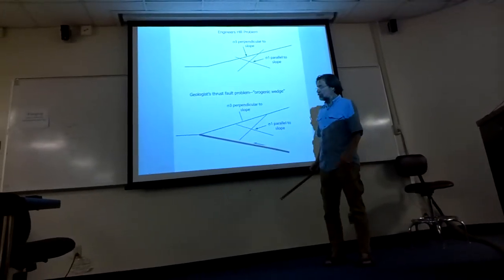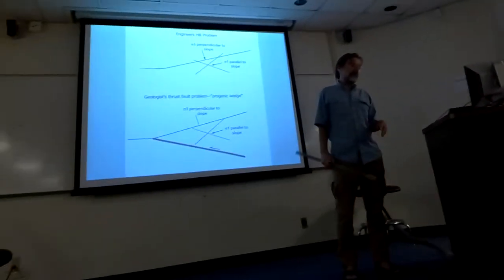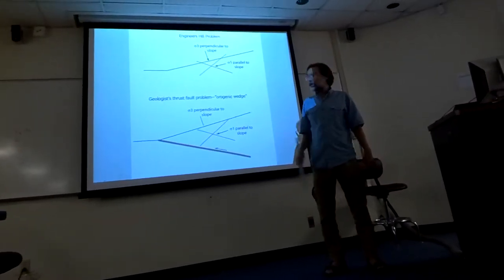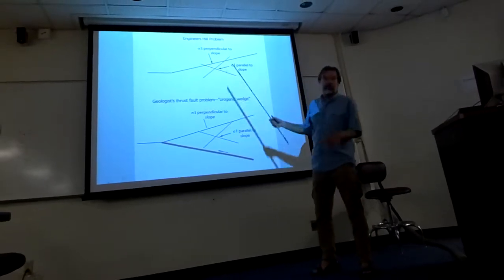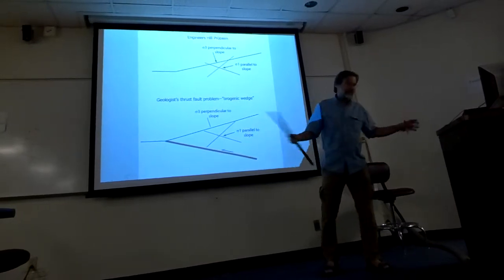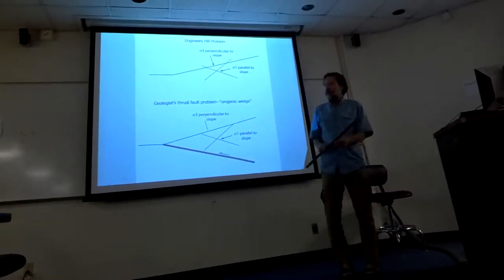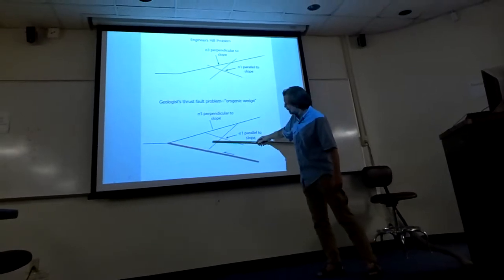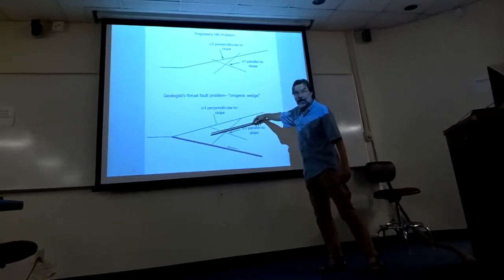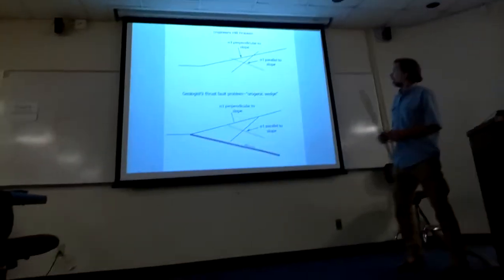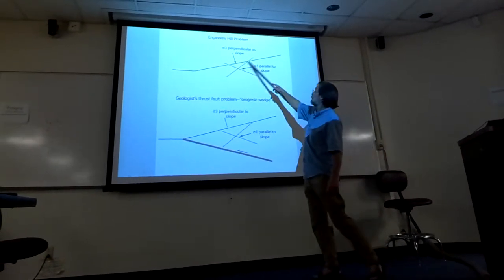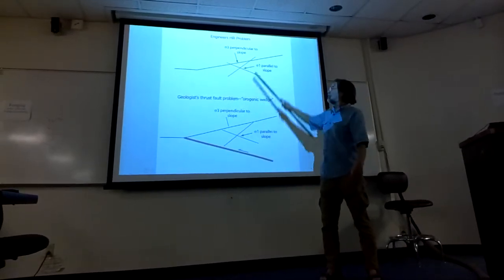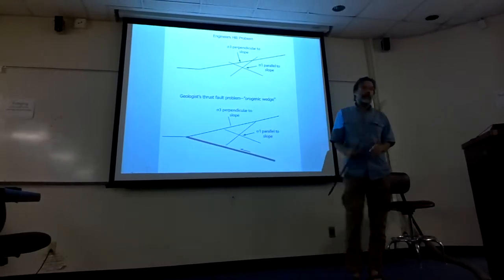So now one part of the paradox doesn't even exist, the fact that you shouldn't even have sliding on the surface. You've got maximum resolved shear stress right along that particular surface, just because of the surface slope. Now there's actually more to this in the sense that there's other things you have to calculate, the elastic stresses and a bunch of things that don't really matter. But the basic part of the story has to do with this surface slope aspect and the fact that, even though the material is compressing in this direction, the stresses are actually inclined because of the surface slope. And this is the engineer's problem, right? This is a big deal if you're looking at slope stability on a surface, because you can have surfaces that you don't think necessarily would be a big deal, but if they have the perfectly inclined stresses on those surfaces, then you've got to worry about it.